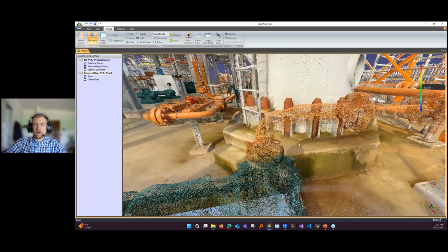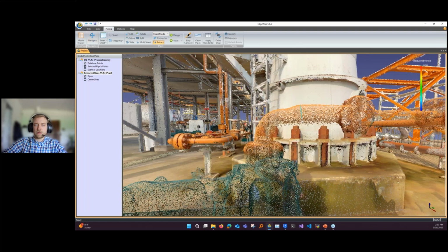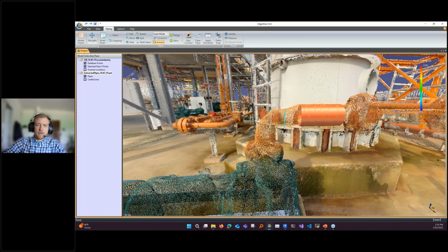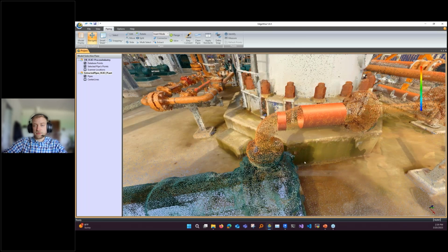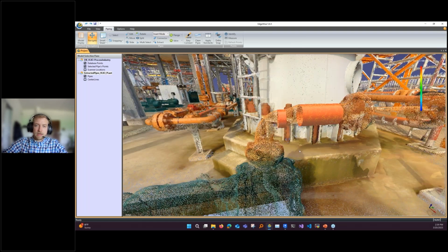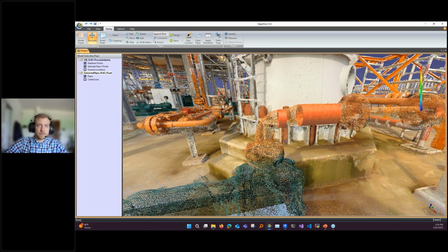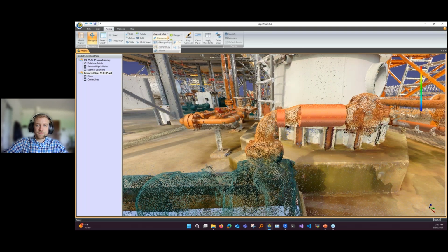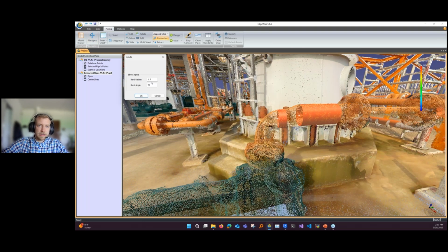So we'll do the rest of the segments like normal. We're going to do extraction here, a little extraction. But to create this elbow, there are a couple different ways to do it that can be pretty sneaky. I'm going to jump into a copy paste type thing. There are tons of ways to do this. There's an append function where, instead of doing a connection, we can just make an elbow, and I can put it here. We're going to do a 1 bend radius and leave it at 90 degrees. It's going to just make an elbow.